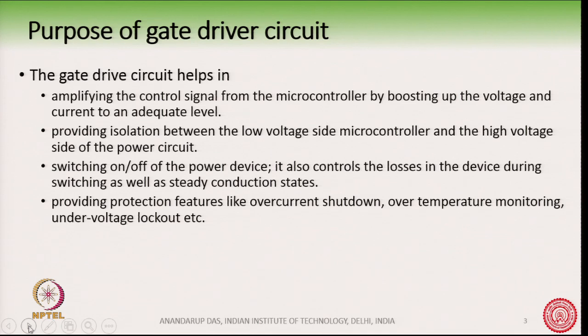And often the gate current or the gate charge required by these devices is quite substantial. Many times we see, for example, that the gate current required by an IGBT or sometimes a silicon carbide MOSFET can be several amperes, 2-3 amperes. The peak gate current can be such high values.